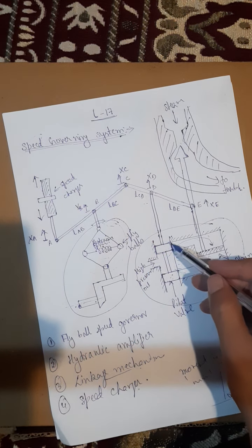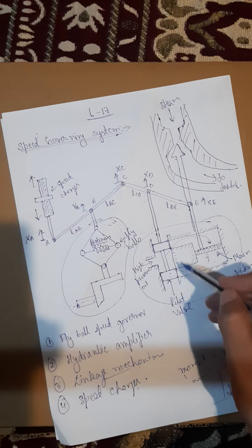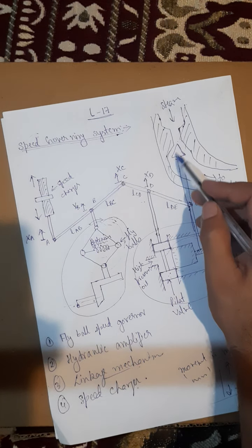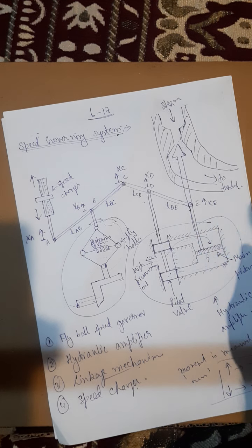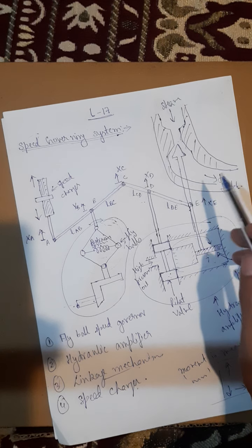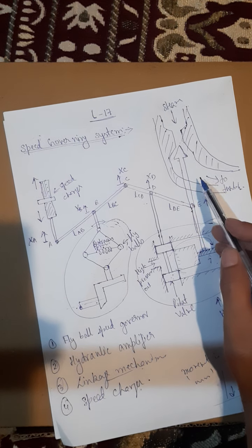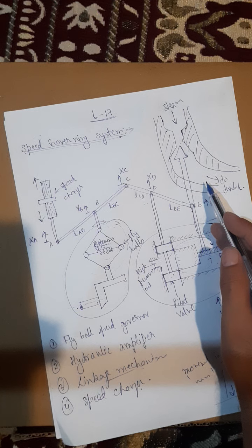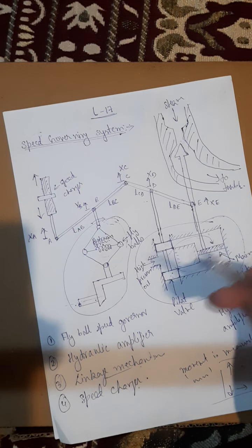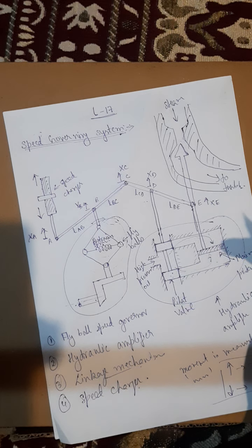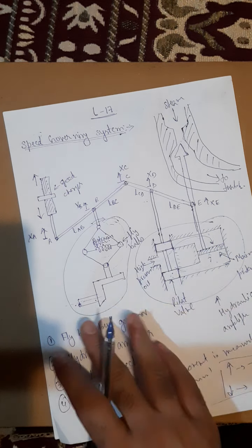Stationary. And we are saying the pilot valve is closed here and closed here. And this steam valve is open by some definite magnitude, so that the turbine rotates at constant speed. At that time the turbine is running at constant speed with turbine power output balancing the generator load, where power generation is equal to the load demand. Got it? So next, these conditions can be characterized. That is steady state conditions.